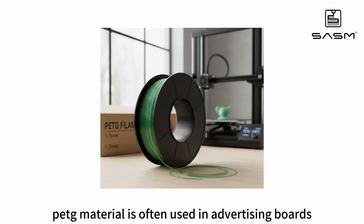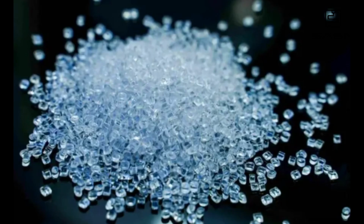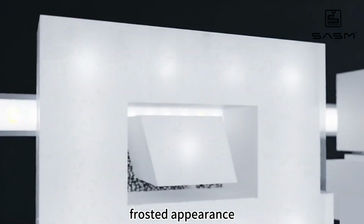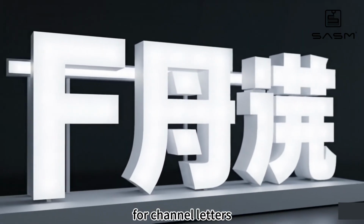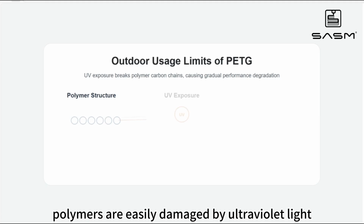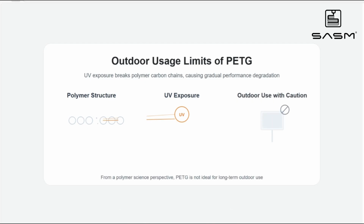PETG. PETG material is often used in advertising boards. Because its raw pellets are transparent, light diffusing powder can be added to create an acrylic-like frosted appearance, which unlocks many application scenarios for channel letters. However, because the carbon chains of plastic polymers are easily damaged by ultraviolet light, from a polymer theory perspective, it is not very suitable for outdoor use.